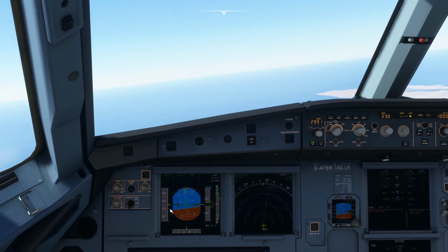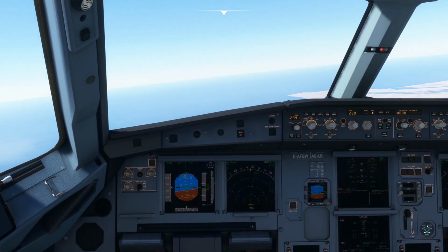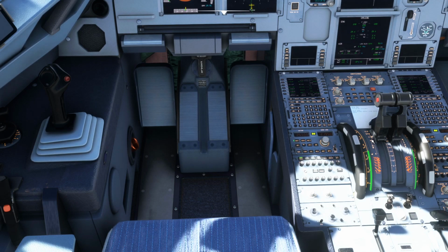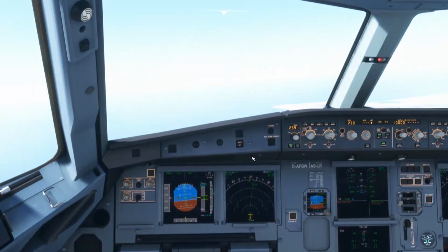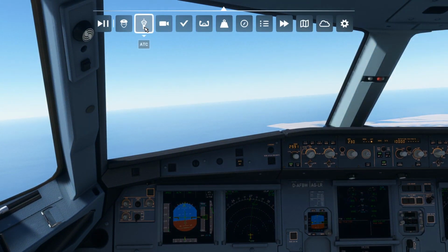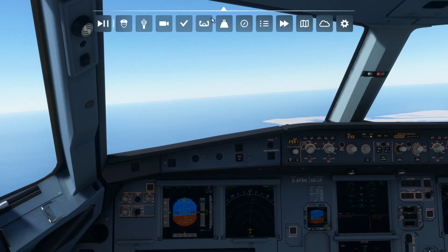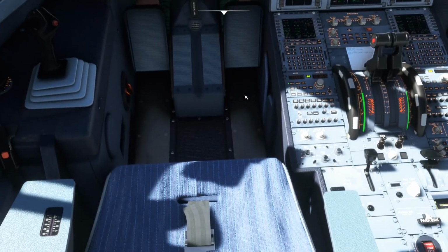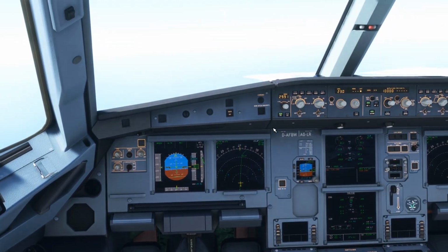This is one point. Another one, at a certain point, 1500 feet, I was supposed to reduce the climb thrust, but while doing this radio communication thing, I missed 1500, and I think at 2200 I reduced it to the climb thrust. But this was kind of a mishap.